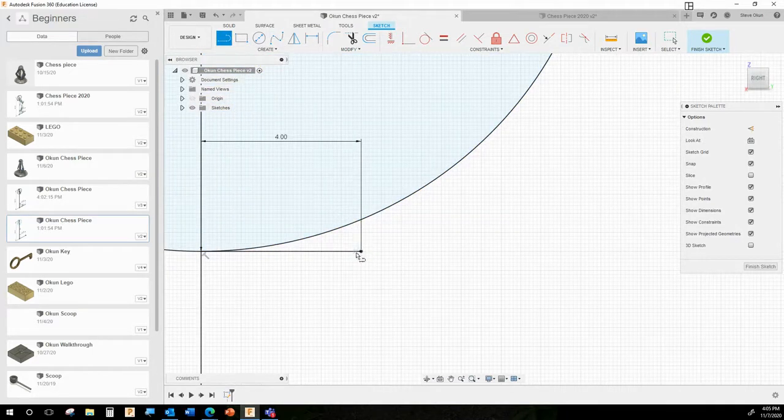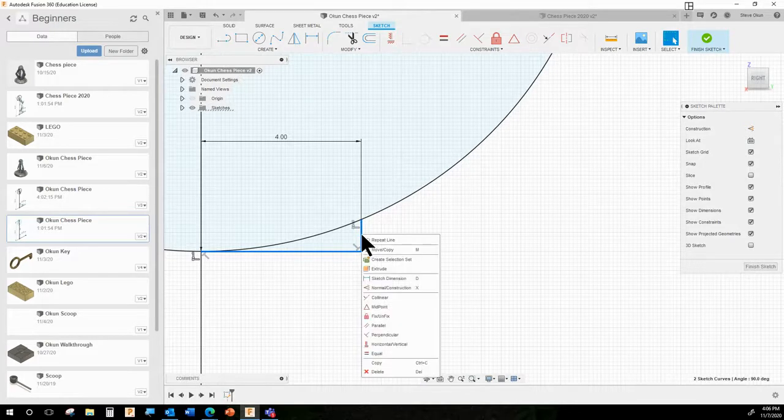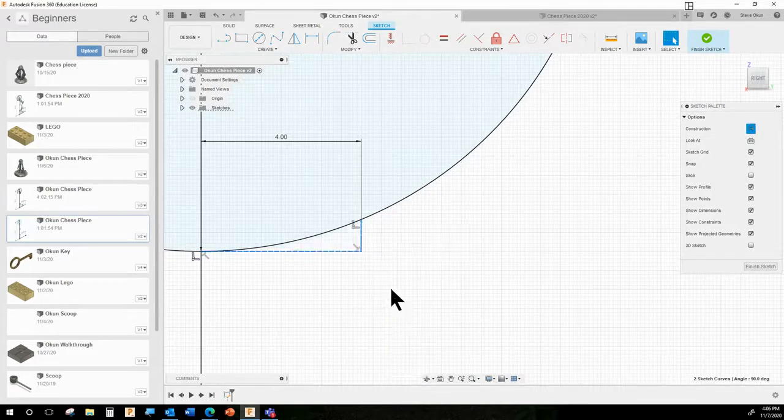I'm going to also draw a line going straight up from that endpoint so that I really see where it's going to connect and I don't have to kind of guess, okay? And so where that turns green, that's an X, and once again, it thinks I have to hit enter to tell it I'm done drawing lines. It thinks I wanted to create a shape, but I didn't. I'm just going to select and shift click and select both and turn those into construction lines as well.